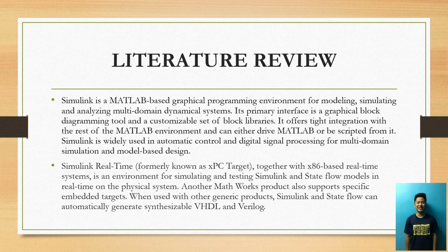Simulink Real-Time, formerly known as xPC Target, together with the x86-based real-time system, is an environment for simulating and testing Simulink and Stateflow models in real time on the physical system. Another MathWorks product also supports specific embedded targets. When used with other generic products, Simulink and Stateflow can automatically generate synthesizable VHDL and Verilog.